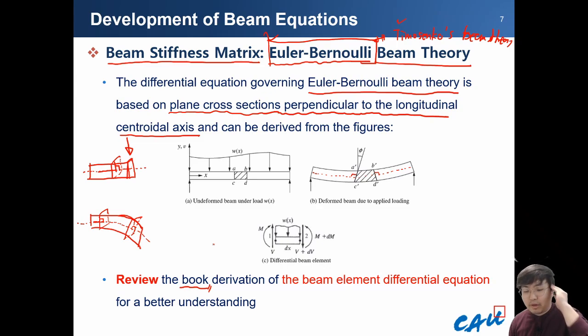I already uploaded some homework and an example of a 2D truss system in COMSOL. There I mentioned that you should obtain the reaction forces and external forces by hand. After obtaining the displacement solution, multiply it with the global stiffness matrix.